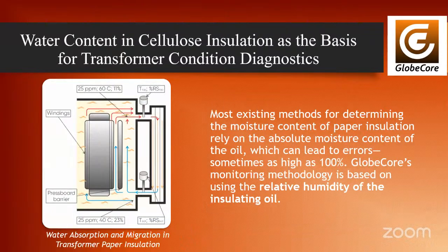It is important to check moisture both in the transformer oil and in the insulation paper. Sensors can directly measure moisture in oil, but the insulation paper is harder. Water always moves between oil and paper, so the oil readings do not always show the real paper condition.